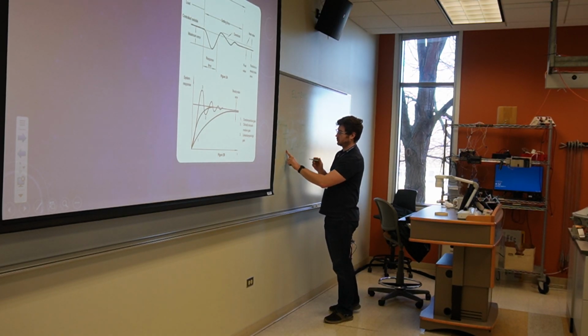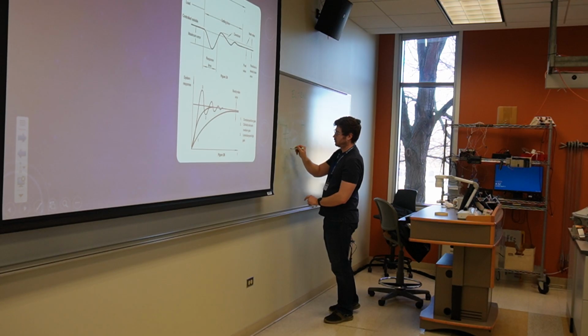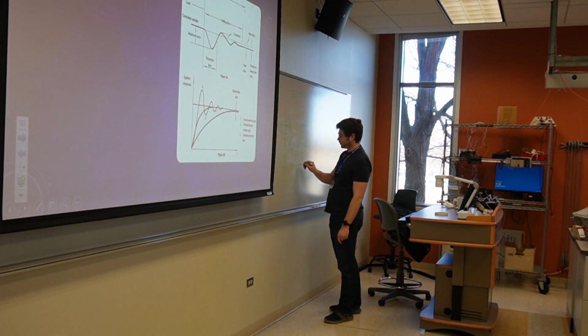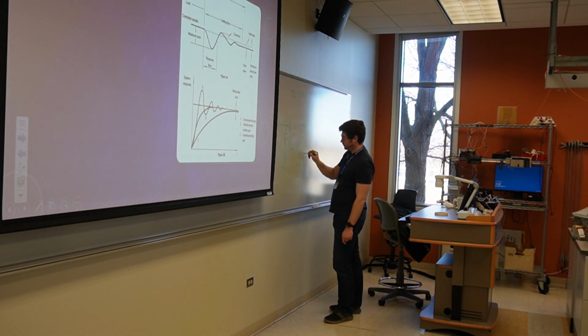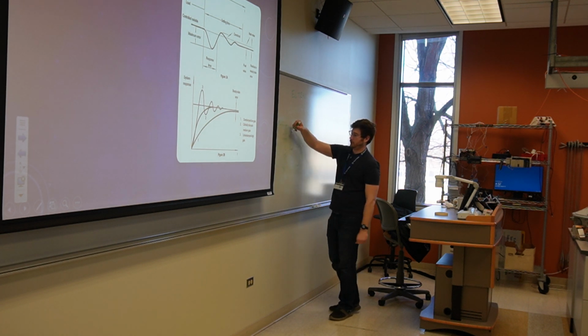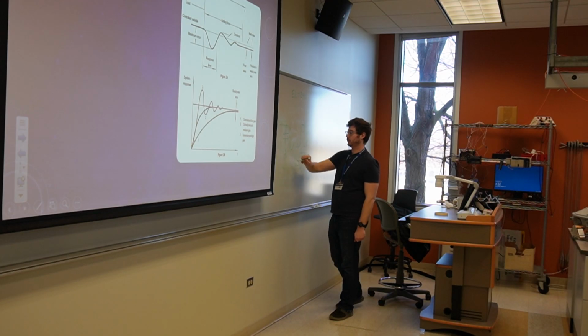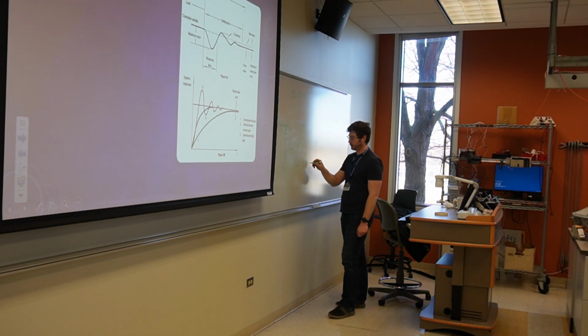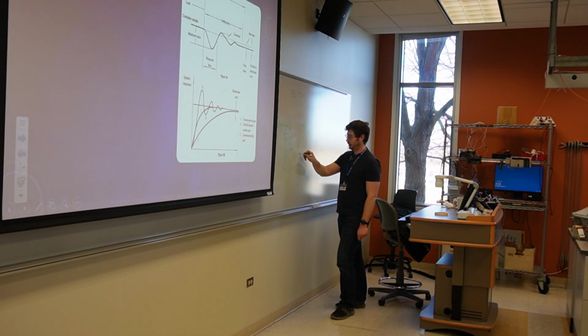Whoops, sorry, it's supposed to be here. It will charge quickly, and then it'll discharge slowly. It'll have this decay, because it takes some time for the capacitor to completely discharge, and the resistor keeps that capacitor from discharging right away. It's kind of like a slow leak in a bucket. So we pulse high, and then the settling time is actually quite long.